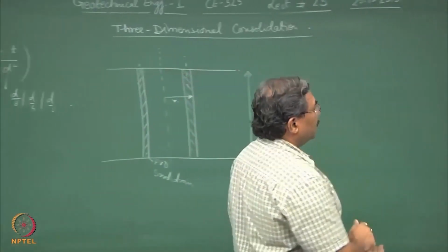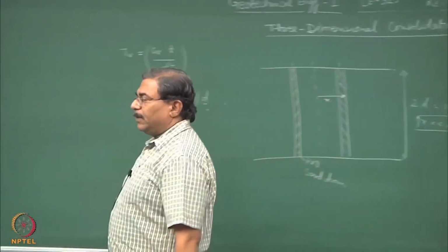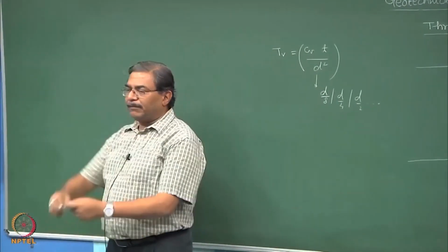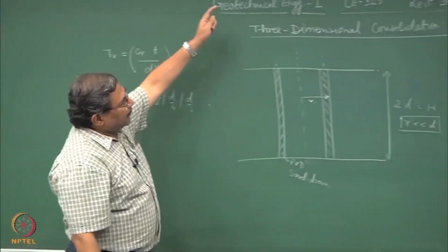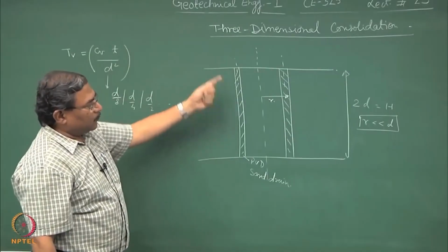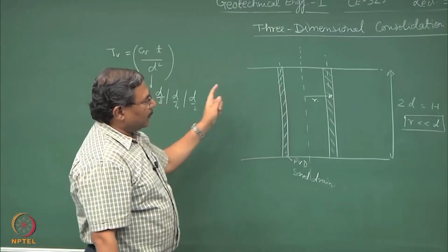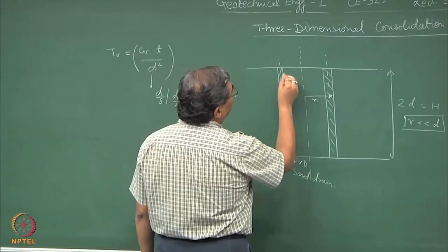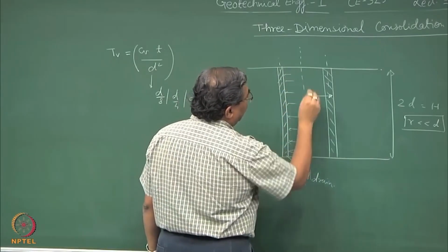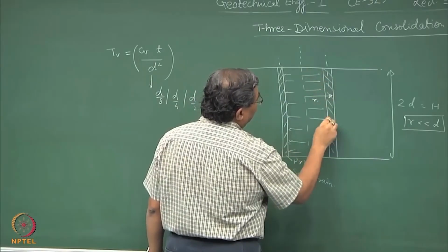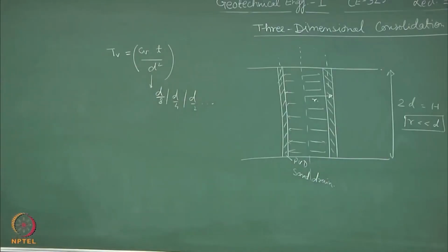This is the concept. I am sure you must have seen most of the projects being done in the country right now, particularly in the coastal regions. You must be seeing big machines inserting something into the ground. With the help of big machines, we can insert the PVDs. These could go up to 20 meters, 22 meters in the ground, and they act as a drain. They take out the water. The water is going to get collected in this, and half of this is like this, and hence the consolidation process becomes faster.